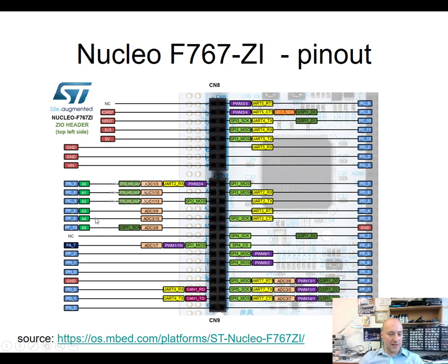And this is the analog input. So the AD converter in the CPU is connected to those pins. So you cannot choose arbitrarily where this analog converter will be connected, but you need to look in such a picture in the documentation.